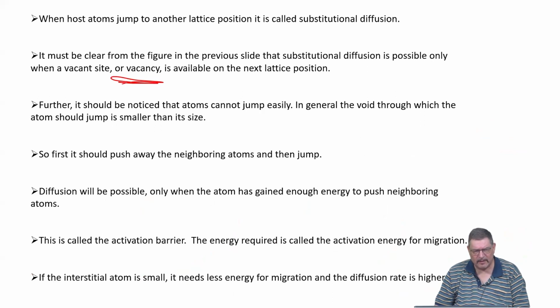And yesterday I already tried to introduce that jumps are not occurring very easily, because when we think of how the elementary cell is filled in densely packed metals, like most of the high entropy systems, there is not an easy way to go from one position where the atom is now situated to the next one that may be vacant, because a vacancy, a quasi-particle, is situated there, since all the other atoms, meaning the electron clouds surrounding the atoms, are kind of in the way.